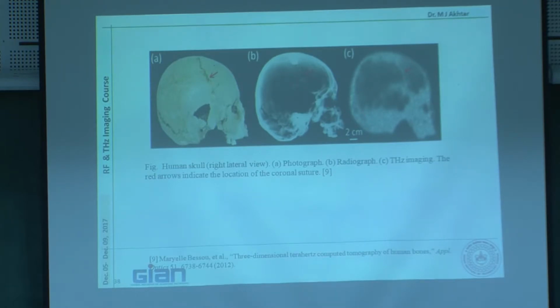The good thing here is that there was some problem, some crack there. In the radiograph you cannot see it, but here you can see it more clearly. In the white portion there is some sort of corner structure, a very small pin-like crack, which you can identify with terahertz but not with a normal radiograph. This is just to show that in some cases terahertz works where the radiograph doesn't. That's the practical aspect.